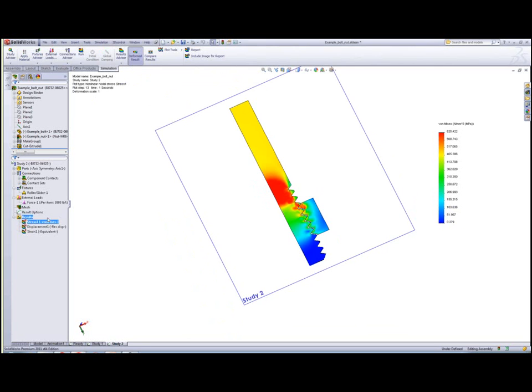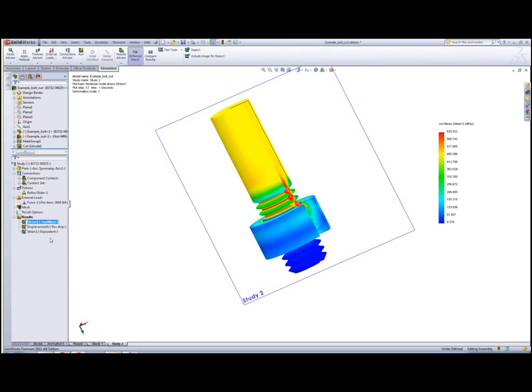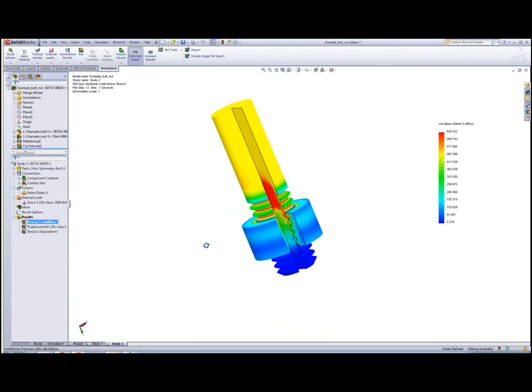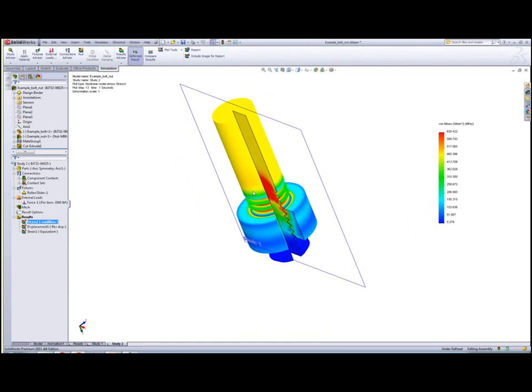So they've added a functionality. If I go into the stress plot, right click and select show as 3D plot, this basically interpolates and revolves that same cross section 360 degrees. And actually you can change that. Let me change this so we can see it on the inside of the model, and so I can see the results a little more clearly.